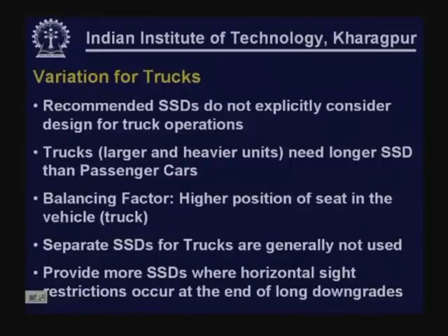However, one must remember that there is a special situation where this greater height of truck drivers will not be meaningful or useful. That is, when horizontal sight restrictions occur at the end of long downgrades.